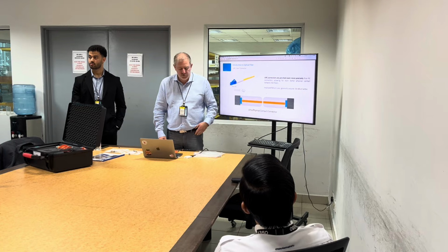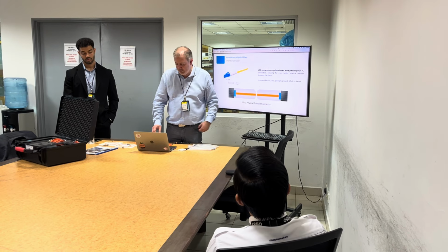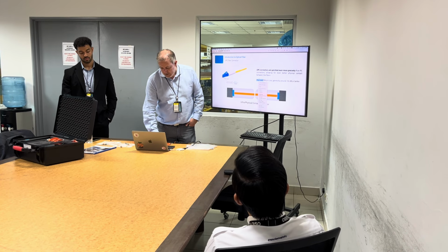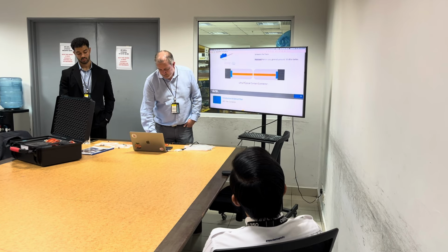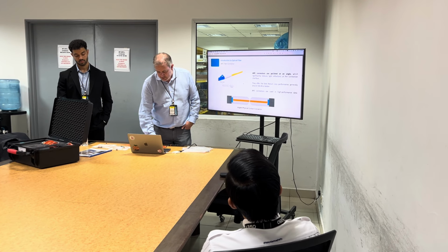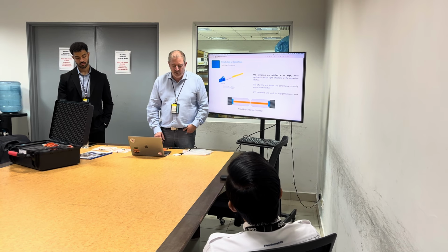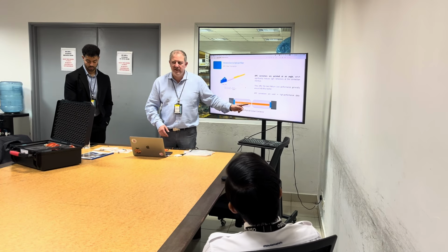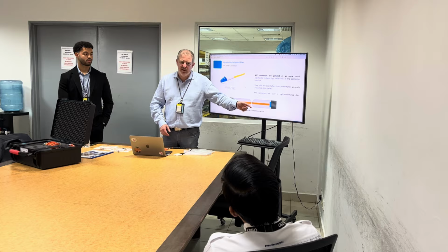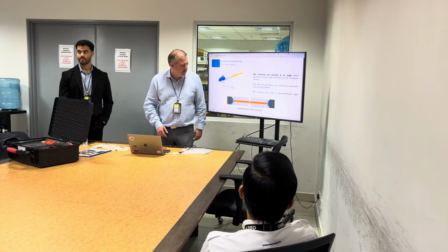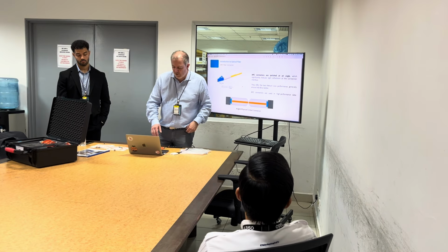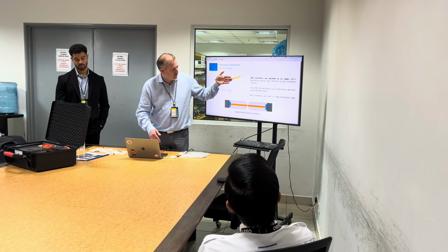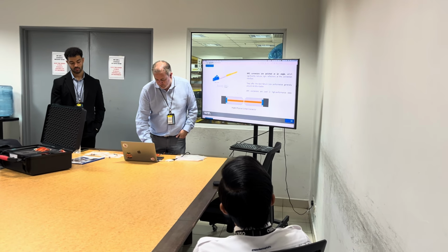And the return loss is minus 50 dB. If I go to this APC connector, it has an angle. Putting in an angle also maximizes the light which is transmitted from one side to the other. So just to give you some examples, every time the performance is even better.